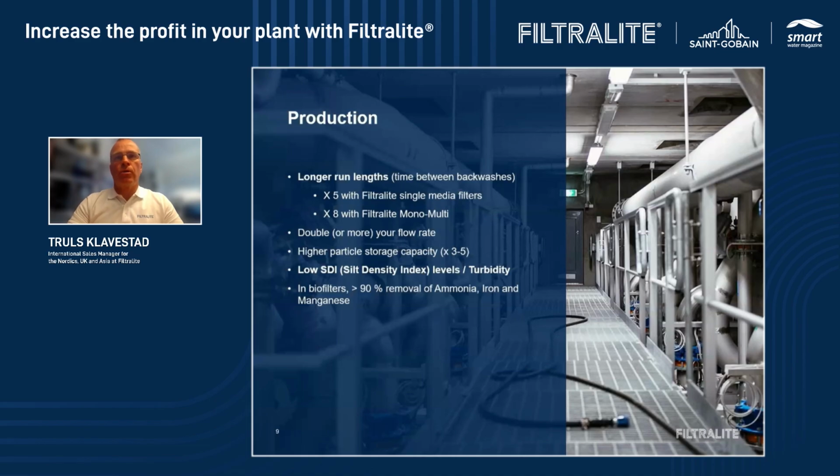And that also means, if all conditions are the same, you have the same grain size and the same depth, then you will get better water quality, if you measure that in SDI or turbidity. So if you have a filter with exactly the same conditions, but one with sand or sand anthracite and the other with Filtralite, you will get better water quality.